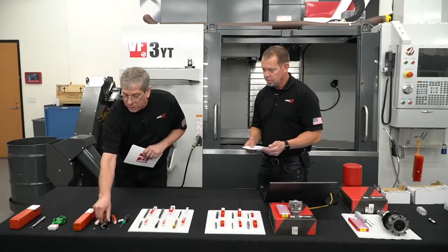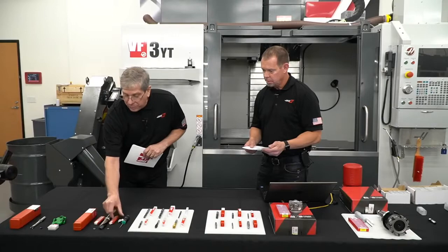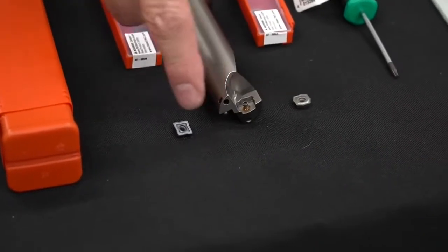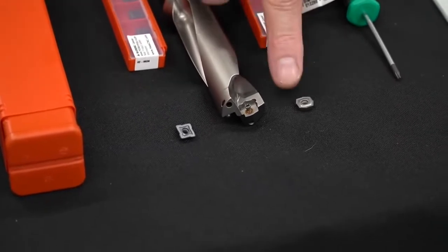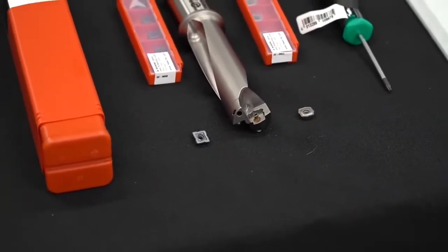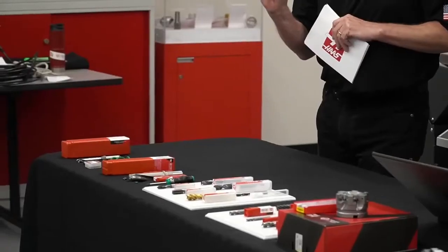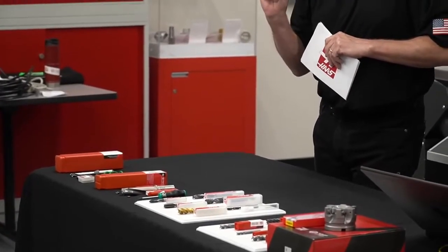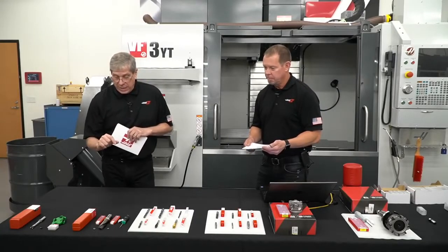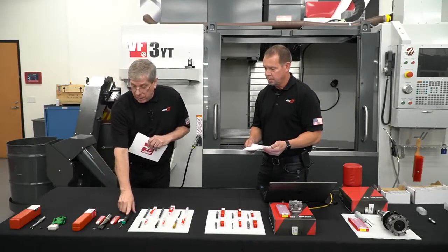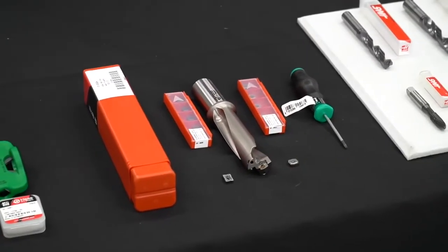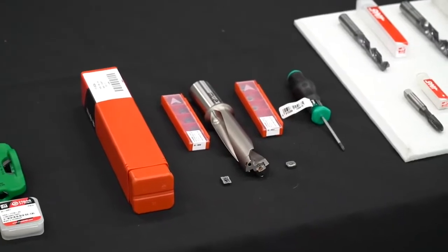So it's really nice because they design the inserts to perform better at the periphery of this drill, and this one to perform better on the inside of the drill. So they cut fantastic and produce a really good finish, but also produce the holes very, very close to the specified size. So fantastic. And then each of the insert drill bodies comes with the Torx wrench to loosen and tighten the screws for installation.